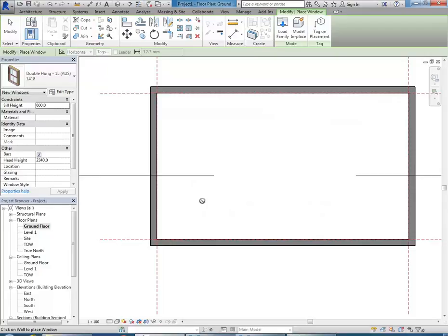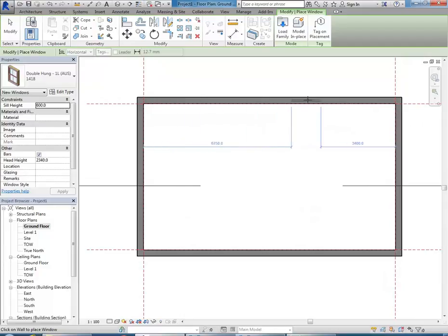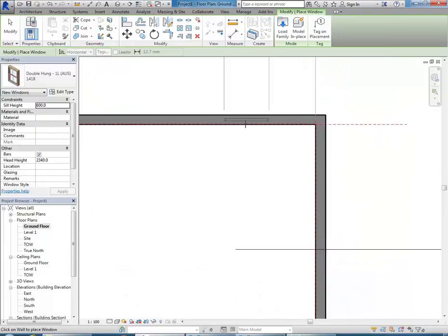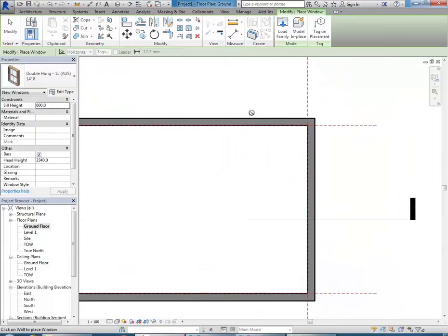What I'm tempted to do is flip this around and draw it with the windows up the top here, and have the doors on the right. That's how you'll print your plans out. I think that's a pretty good orientation anyway. And that means we don't have to change north either. We've got north already pointing up. Then if you move the cursor onto one of the walls, you should see the window come up there. Don't worry about the exact position, just click to place it in the wall.